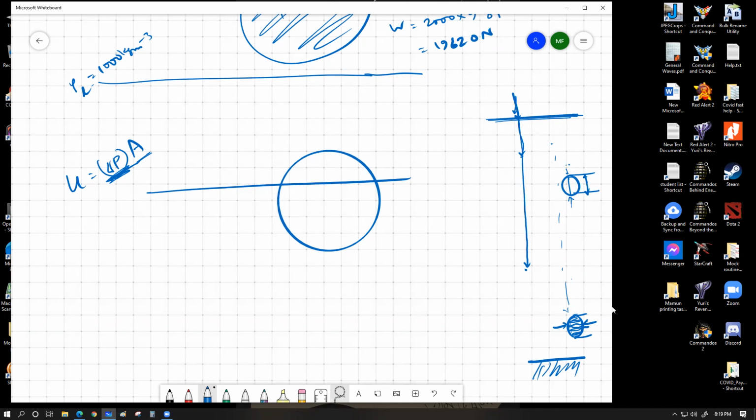For example, let's say over here this pressure is 100 units. I'm not saying kilopascal or megapascal, whatever. Let's say at the bottom side this is 120 units. So the difference is a 20 unit pressure difference. If we go much deeper, this could be 1000 units, and in that case the bottom pressure is going to be 1020 units. The absolute value of pressure is going to be more, but the difference of the pressure is pretty much the same, which means you're going to come across the same amount of upthrust. Yes, sir. Okay.